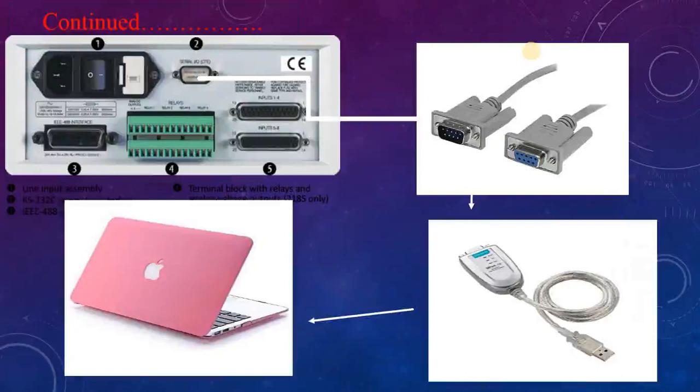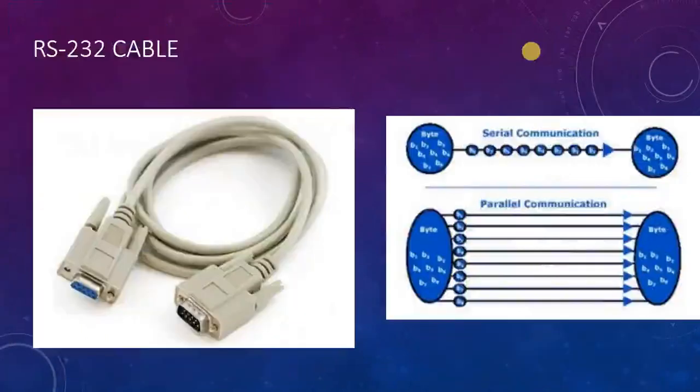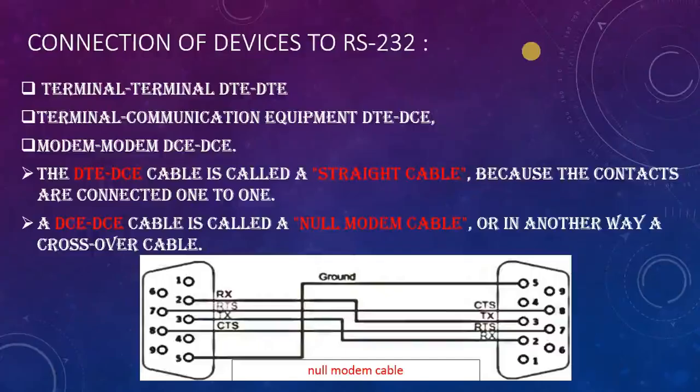This is how the back panel looks. The 9-pin D connector is the RS232 connector. You will make a cable and connect it to the adapter, then connect it to the PC. The cable looks like that. This can be made at home. You can see on the screen the last one, this 9 to 9 pin null modem cable is made like this. In fact you don't need all these 5 wires, but you keep them, but you probably need 2, 3 and 5 on the left hand side, and on the right hand side also 2, 3 and 5. Usually only these 3 wires are required.